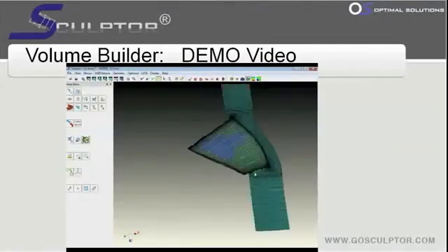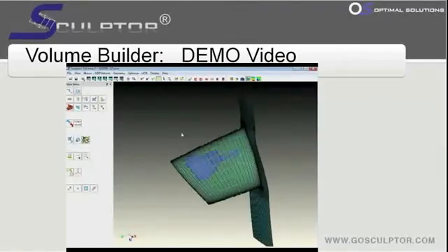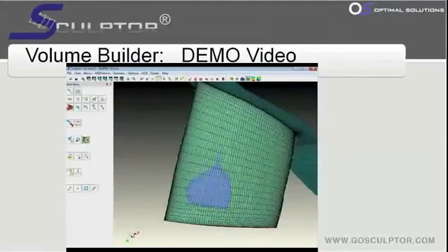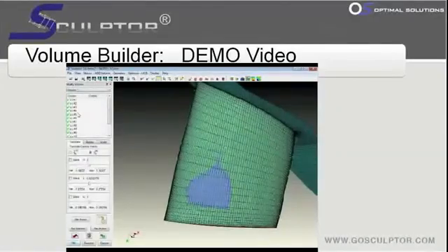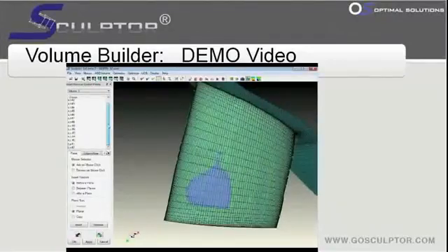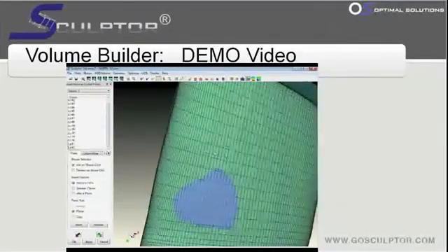But just to set this up, we quickly create these surface control points, and then we go to the next step of creating a far field set of points that give us the ability of the surface control points to smoothly morph the shape out into the flow domain, so that the flow domain remains a high cell quality mesh for the subsequent calculations in the CFD solver.